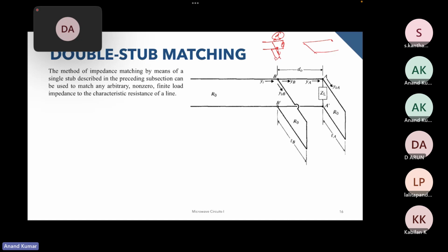a very small PCB with a number of traces going at some places, and we are trying to match this component to this value, and we might end up with this particular distance at a place where there is another trace running next to it. There is another trace in this direction, so we cannot add a short circuit stub over here, or whatever length this is coming. But it might happen that this trace bends over here and this trace bends over here, and we are comfortable with adding a stub over here.